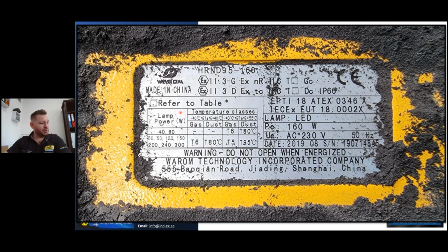Also, as Tom Waite said, you would consider the housekeeping of the installation, yes, the buildup of dust on the equipment. Also, the layout of the facility. Are there buildings within buildings? Are the roofs flat surfaces? Are there other flat surfaces for dust to land on? If there were walkways with no holes, that's dangerous because dust is layering and getting kicked up as people go along. So there are different structural and mechanical requirements where good design of a facility is really important.